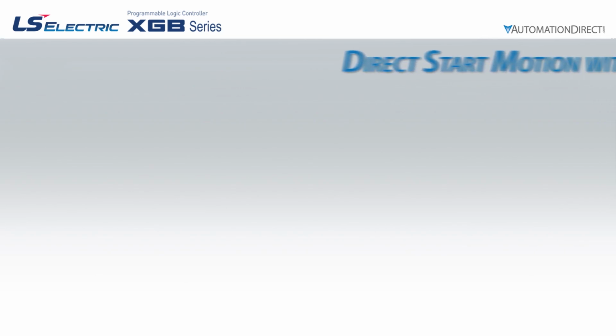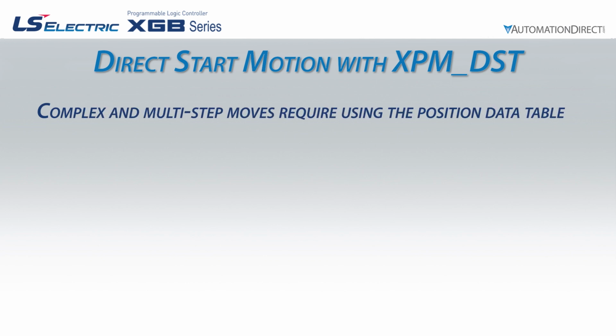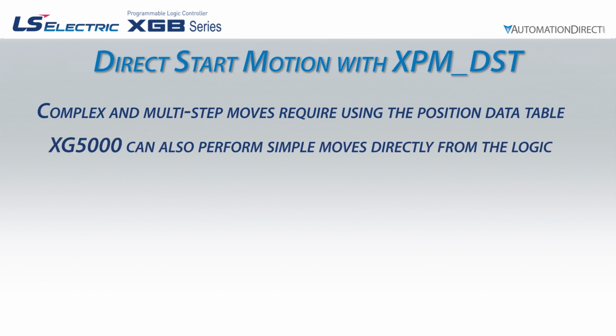The LS Electric XGB has multiple ways to initiate motion. Complex moves and sequential moves will use the position data table in the XGPM software to define these moves, and then use various function blocks in the XG5000 programming software to call them up. However, the XGB also supports a direct start function, which allows us to define the move directly from the logic in XG5000 without referencing the position data table.